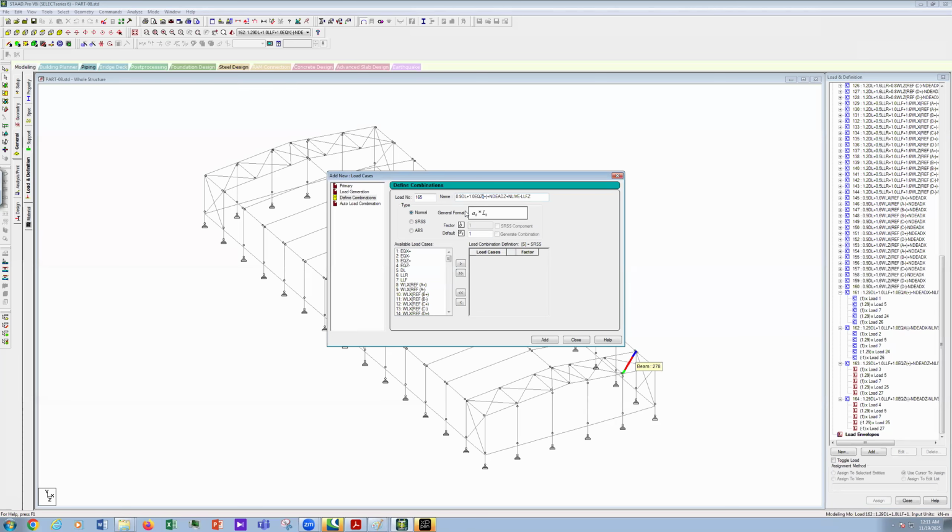So now this is X, X. We don't have any notional load for live. Okay, so this one is also X. So 0.9, so 1.0, EX and dead load and X for notional, X direction. Now again, this one doesn't have a live load. Okay, so this is our value. So this is 1, and this is 0.9, and this is 0.